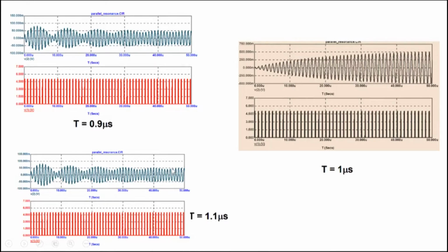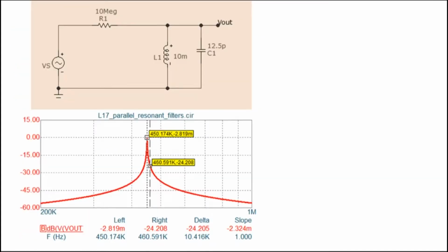So this is the concept that we want to utilize for obtaining very high selectivity. Use the concept of resonance. The signal that you want to capture or pass, let that signal match the resonant frequency of the circuit. And the rest of the signals will be out of resonance with the circuit and will get naturally attenuated and rejected. So let me show an example here.